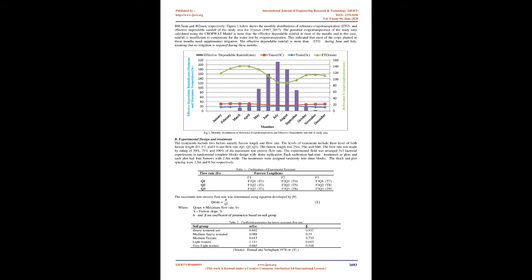Furrow irrigation, reported to be one of the least efficient methods compared with other irrigation methods [5], is still one of the most widely used forms of surface irrigation, despite its application efficiency remaining relatively low [6]. Not enough effort is being made to keep improving its management and efficiency. There is a need for basic technical parameters such as flow rate, furrow length, and cut-off time that easily apply to furrow irrigation system design in order to optimize for local conditions [7].